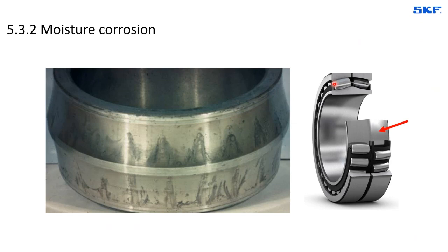And when the seals of the bearing housing and the arrangement of the seals is not good enough, or has been worn out, or there is some other issue, the corrosive media enters, and then what we see in this picture, again in a ring of a spherical roller bearing, is a certain pattern in the distance between these marks. And when you overlap the cage here, you will see that the distance is exactly the distance between the rollers, the roller pitch.